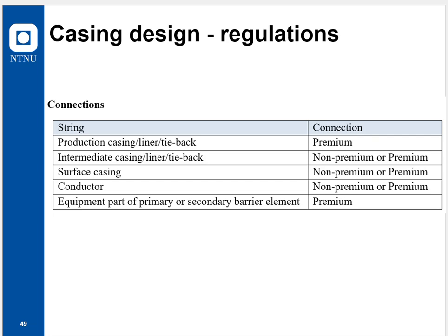What we're talking about would be a situation where, for example, the formation collapses on the casing, and then the mud deteriorates so that the weight material becomes like a plug going into the casing, and you have a situation where the formation frac has increased quite significantly from the theoretical.